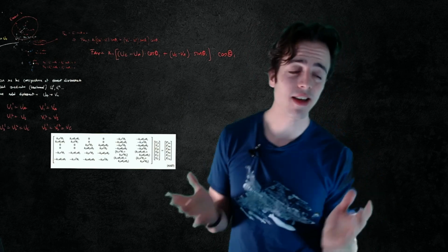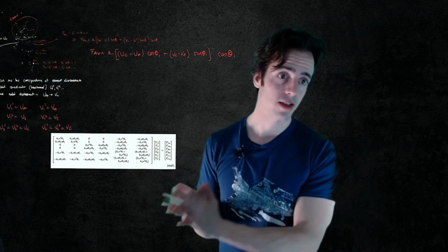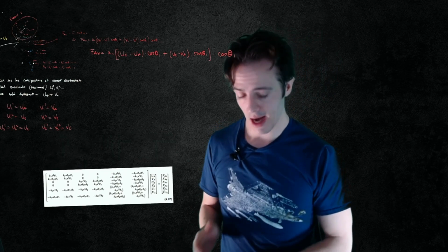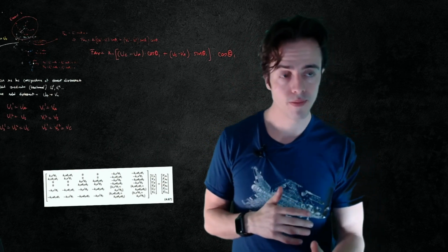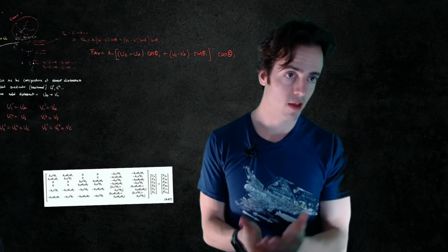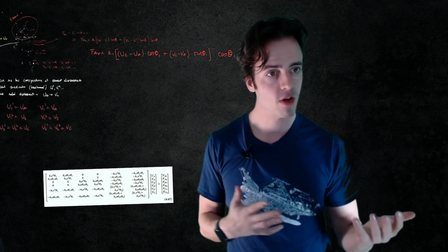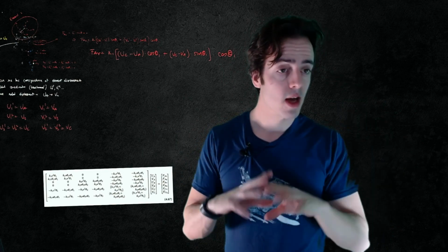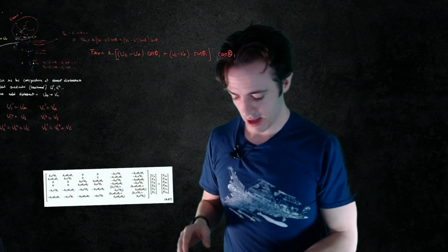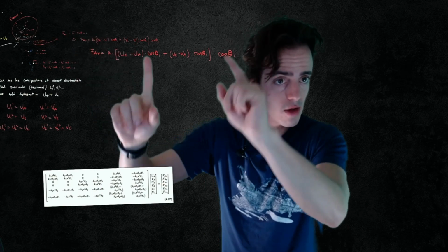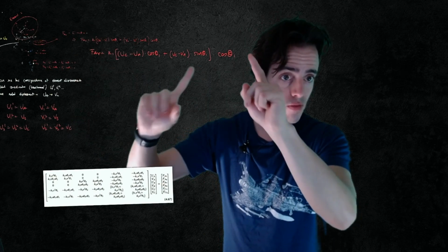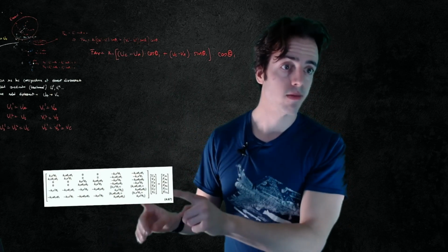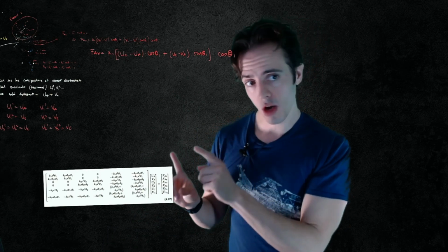What we're really going to see is that this is really difficult to do by hand. But what we've done is come up with a procedure that follows the same steps each time. We're taking local coordinates, transforming them, looking for correspondence between local coordinates and these global nodal displacements, and formulating a relationship based upon our constitutive relationship up here. That directly enables us to come up with a bunch of equations that we can put into matrix form, and this describes our entire problem.